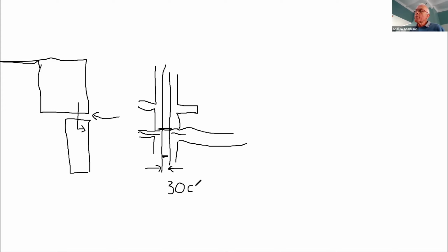For a 10-story building, we might need a 60 centimeter gap between the buildings, but it depends on the height of the building and the flexibility. And really you have to look at one of the pages of my book to get more information about that, because it's rather complicated. Does that answer your question?